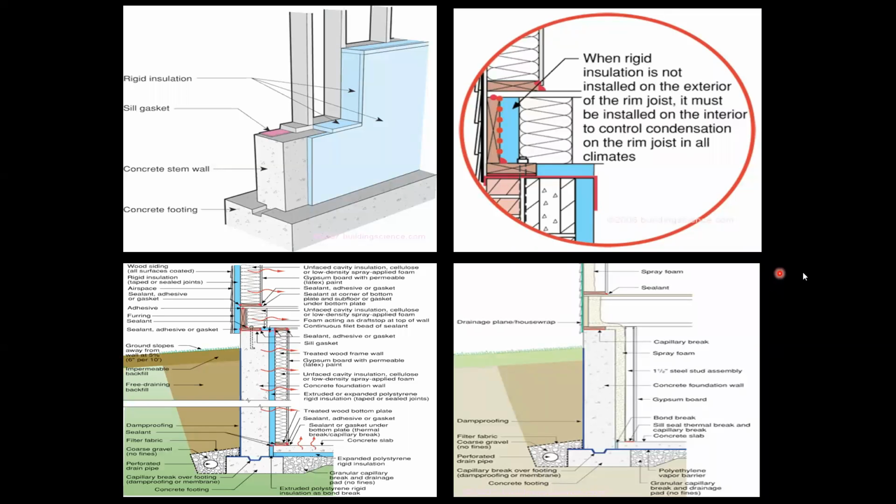This is a little bit more about insulation, and this is really in floor spaces. We're talking about areas like this that get missed easily. Even the sill gaskets, you really should have a seal right here, some kind of flexible sealant that can move. We've actually got 3, or 4 if you count the rigid, different materials.